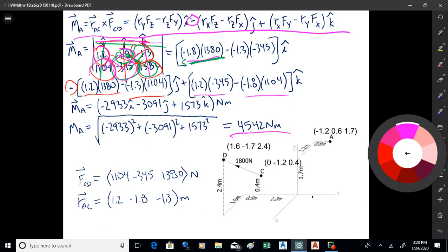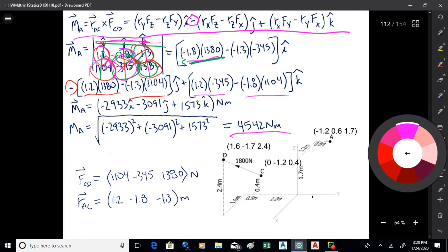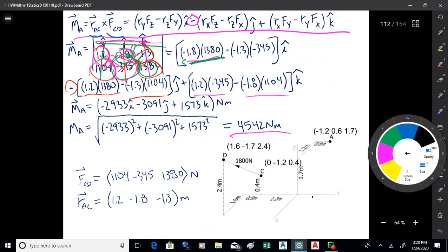Okay. Now, two important points on this. One is it's R cross F. That's the formula. Remember to do it in the proper order. R crossed with F. So R first, F second. The other thing is the vector goes from the point to the force, A to C. If you make an error on either of those, you'll get sign errors. You'll just have the negative of what you're supposed to get. If you do two errors, you'll get two sign errors, you'll get the proper numeric answer, but you aren't doing it correctly, so that won't be right, okay? So just remember to get this stuff right. Right order, right signs, all that stuff, okay?